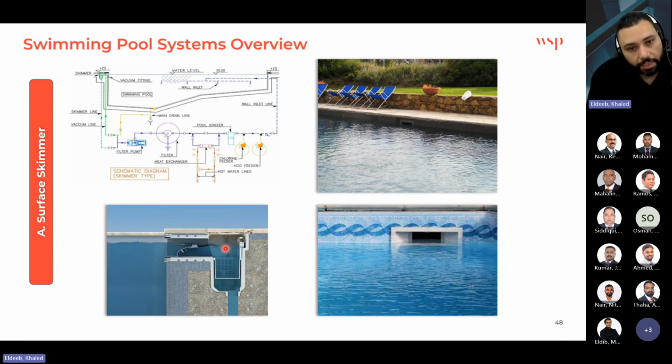But what I'm telling you is, from my experience working in handover, the air temperature should be in the specs also. You should make the temperature of the air inside the pool higher than the temperature of the water itself. Otherwise, the evaporation will be too much, and it will cause condensation everywhere. So not a dehumidifier; we should adjust the air temperature, but this is not covered in our course.